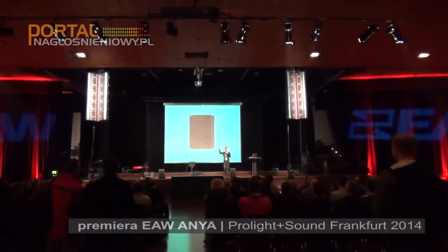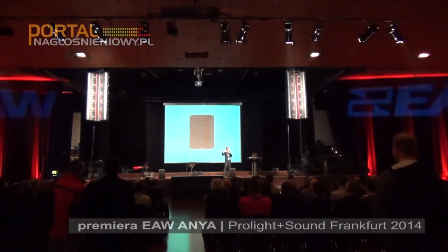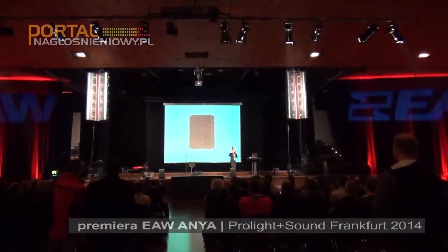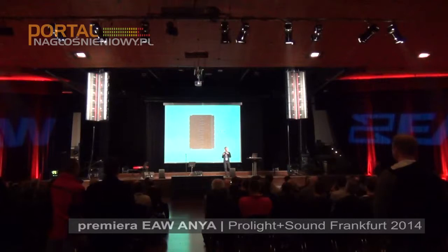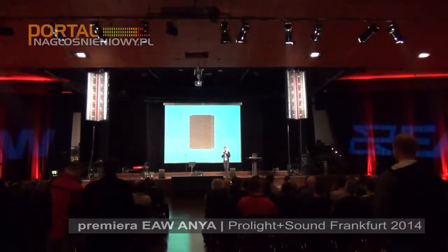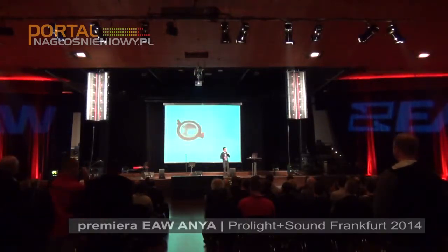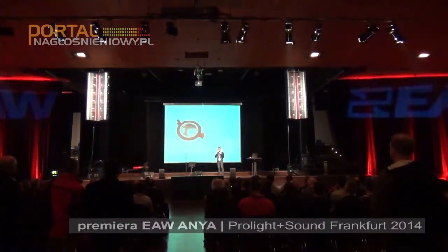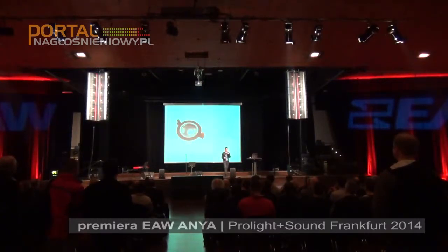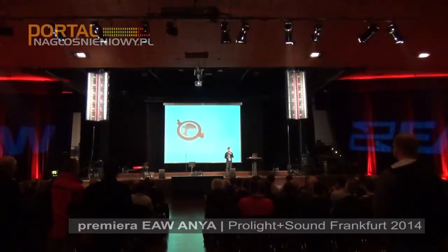And we actually set the bar a little bit higher for ourselves when we were designing Anya, because it is such a radically different and high-level system. We actually wanted to reduce the spacing from what we had achieved in DSA, which was much closer to 3 centimeters. For Anya, we set the target at 2.5 centimeters. And of course, this meant that we couldn't rely on the typical compression driver size that we would use in a system of this scale. We had to go to something much, much smaller.